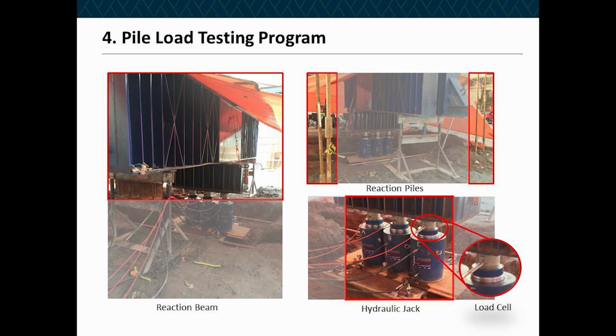So let me show you a little bit more about the pile load testing program. These are some pictures of the test. The figure shows the pile load scheme, where you can see the hydraulic jack, which applies the load, and that reacts against the reaction frame. In this case, we had 4 reaction piles to resist the forces. Also, an important piece of equipment is the load cell, which allows the loads to be read with more accuracy.